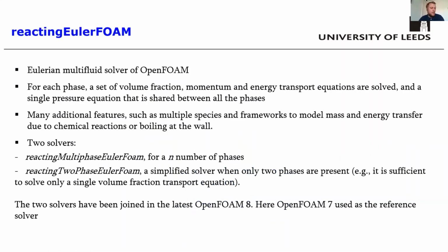Let's start. So both cases will be based on the use of reacting Euler foam, which is essentially the Eulerian multifluid solver that is implemented in OpenFOAM. And what this solver does is solve a set of conservation equations for mass, momentum, and energy for each of the phases, and a single pressure equation that is shared between all these phases.